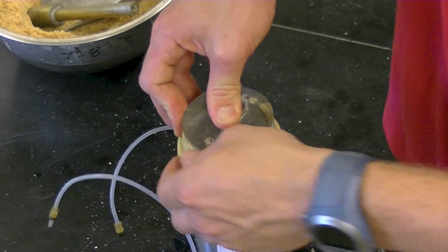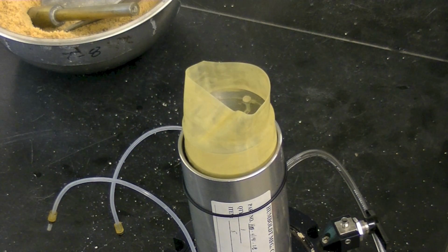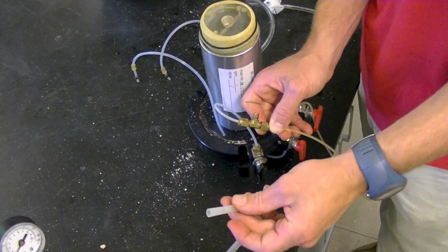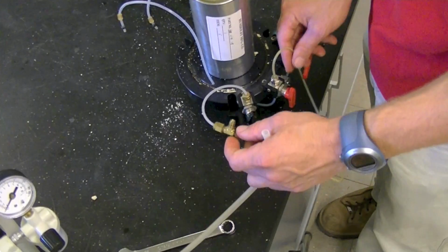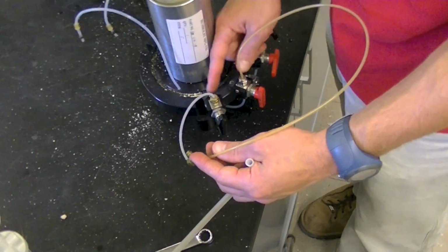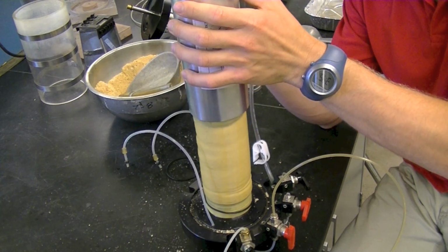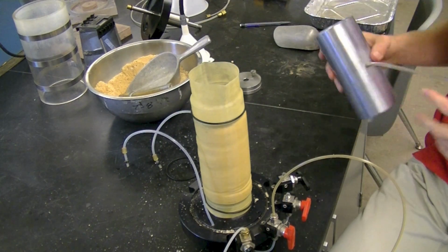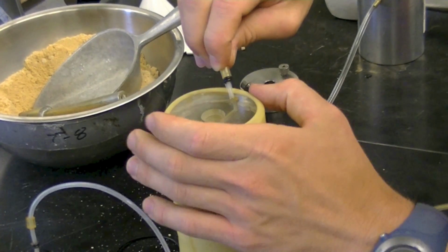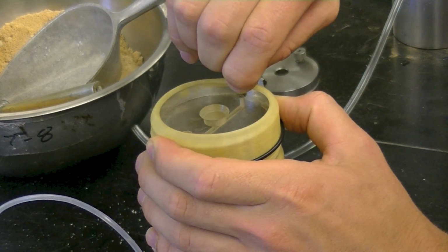Slide the top end of the membrane off the mold and onto the top platen. Once the membrane fully covers the top platen, bridge the top and bottom nozzles with tubing. Connect the vacuum to the bridge line so that the sample will remain upright after removing the mold. Carefully remove the mold. Slide the O-ring down onto the top platen to seal off the top. Connect the drain lines to the top platen by pushing or screwing them into the inlets.